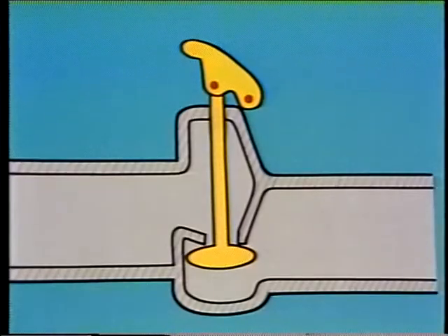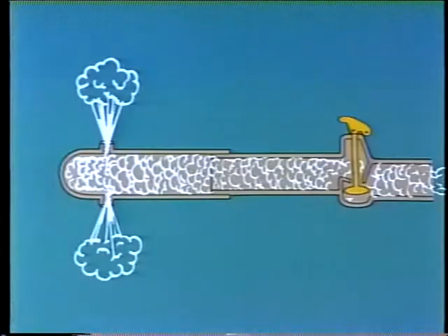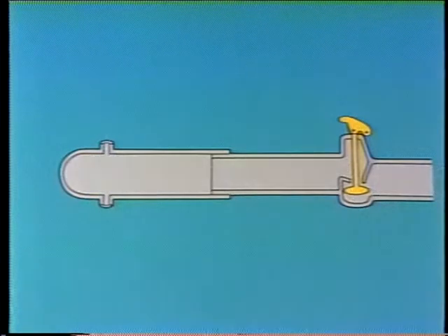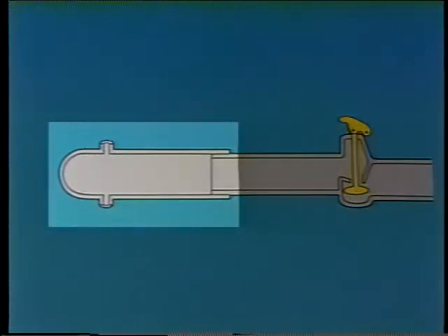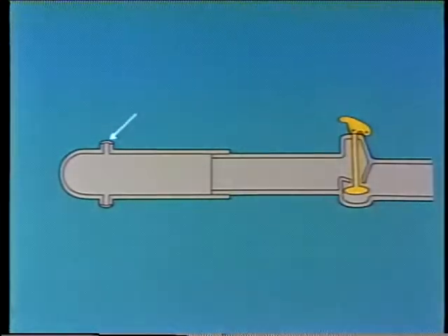When the valve is opened, the blowing medium is fed through the feed tube to the soot blower's blowing element. This blowing element is the only part of the soot blower that actually extends into the boiler. It has one or more nozzles that direct the blowing medium over the surfaces that have to be cleaned.